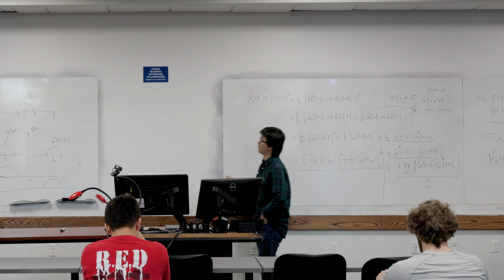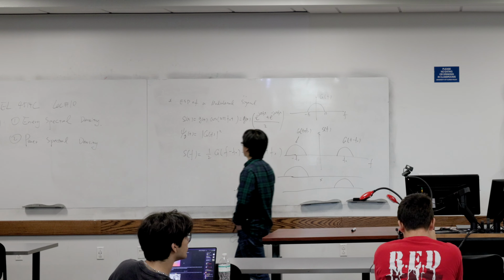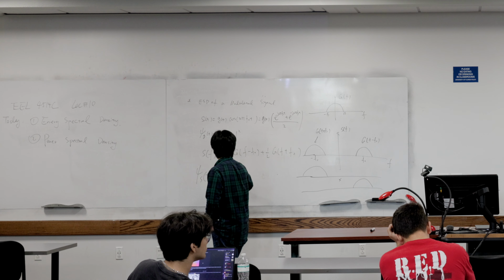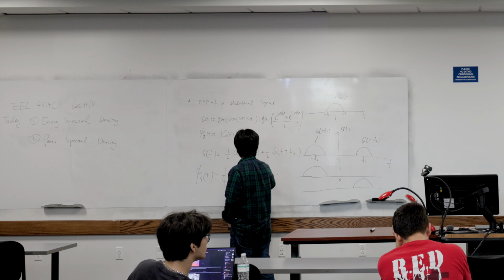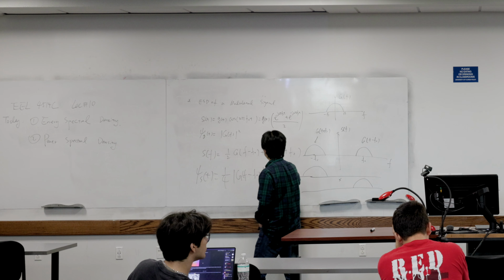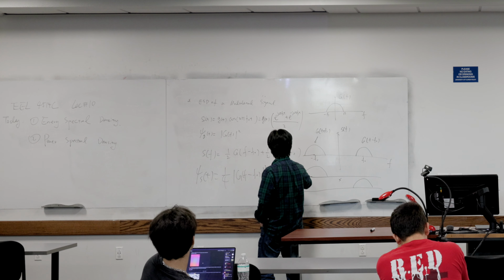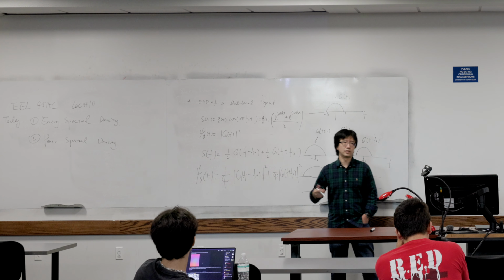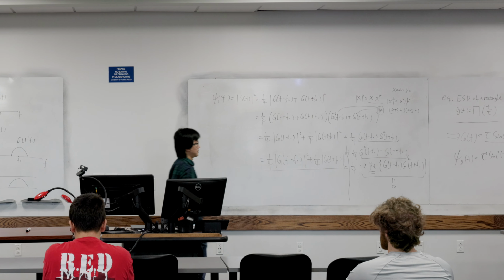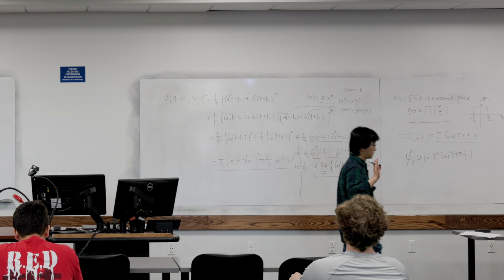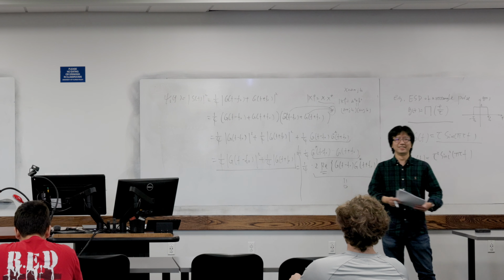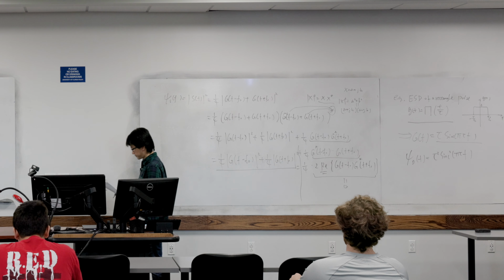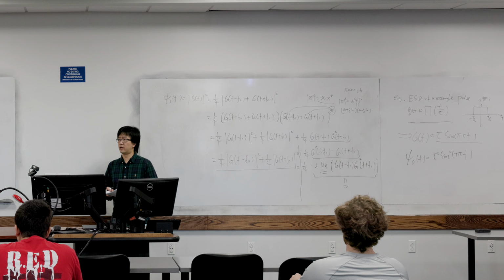So basically, maybe I can write here again to make it explicit. The power spectrum density of S is nothing but 1/4 |G(f − f0)|² plus 1/4 |G(f + f0)|². Right, so that's the power spectrum. That's the energy spectrum density. Yeah, I keep calling it the power spectrum density because that is what we use in practice. Okay. Anyway, that's what it is. Okay, are we good?